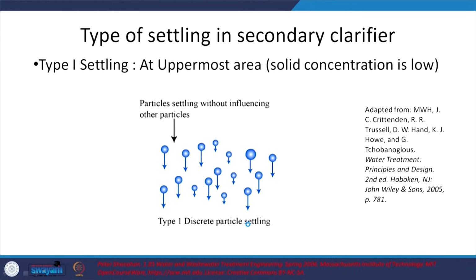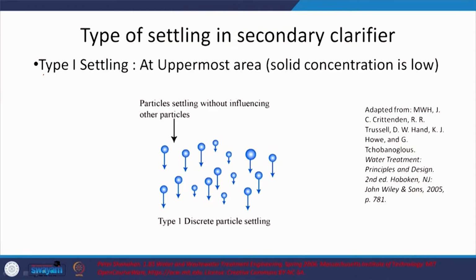What are the types of settling we will encounter? In general, if you look at it holistically, in the top zone, how is the clarification occurring? You have solids coming down. So, you can say it is maybe zone settling, because we saw this in our video, where I just took out the MLSS, put it there and it settled within 30-40 seconds. Thickening, we did not see that there, but it is not so straightforward, right. Let us see where else or what other kinds of settling we take a look at.